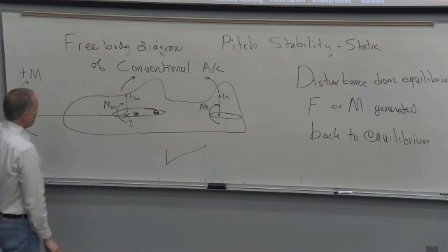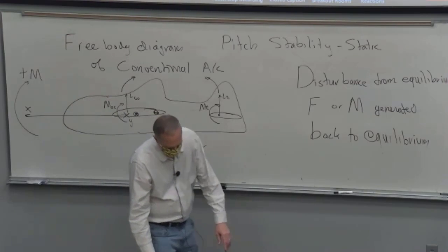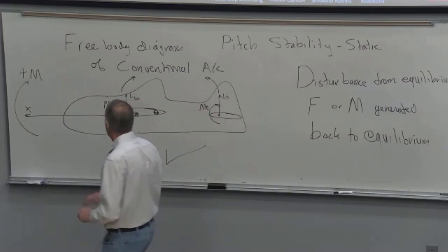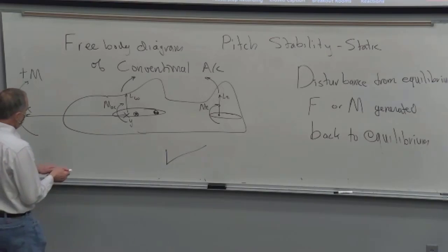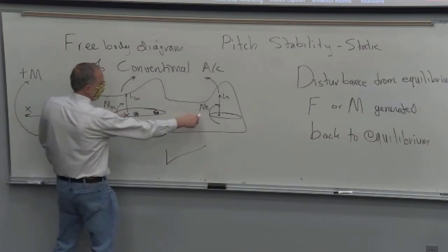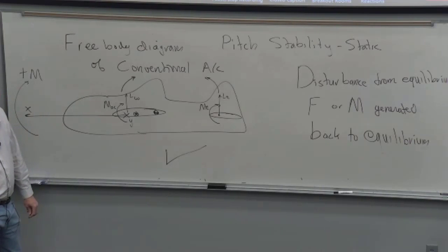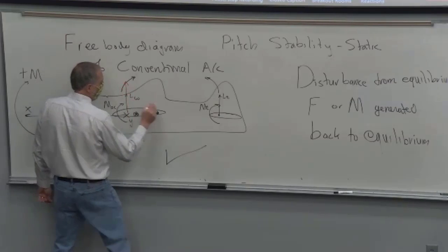So pitch trim. How about stability? We're talking about now the angle of attack changing. Maybe a gust, or the airplane pitches up for some reason. So we know that the pitching moments stay the same with angle of attack, and we'll write this out in equations. We're just talking through it. But these lifts are going to change.